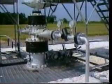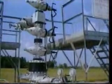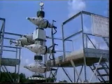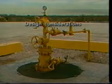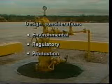In this module, we shall follow the path of the flowing fluid, starting first with the wellhead equipment and moving on to the flow control equipment, the Christmas tree, and downstream flow lines. The wellhead links the downhole equipment to the surface equipment. Wellhead design is predicated on casing design, which in turn is predicated on environmental, regulatory, and production considerations.